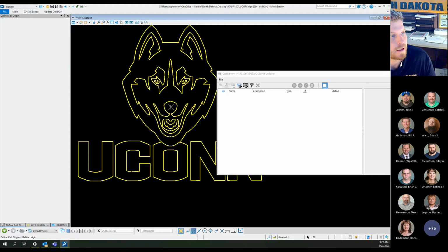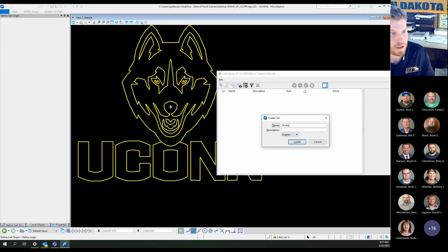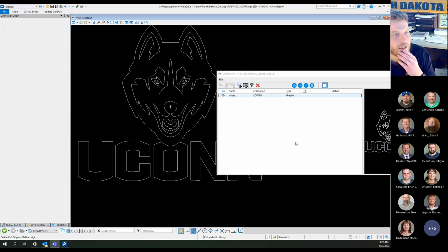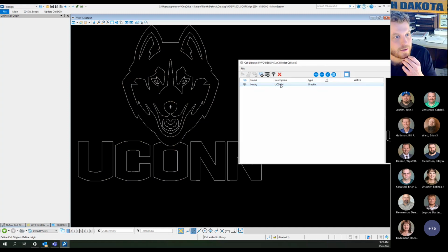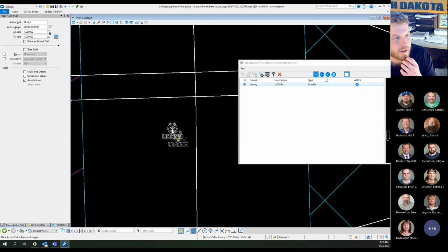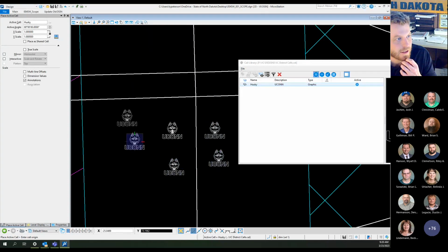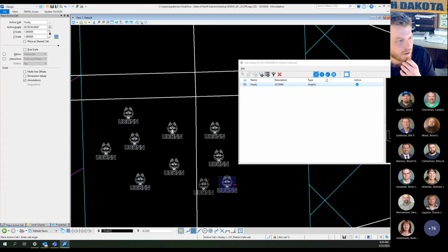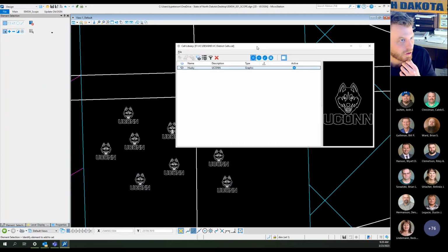So I'm going to click this, and you can see that this create button became active. I'm going to hit that, and you just got to give it a name. I'm going to call this Husky, and I'll just say Yukon, and leave that as a graphic. And I'm going to hit create, and it's done. So all I got to do now is double click that, and now I have a cell, and I can stamp that how many times I want. And that's pretty much all I have for cells and all I have for my presentation.